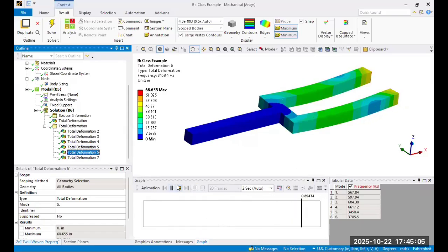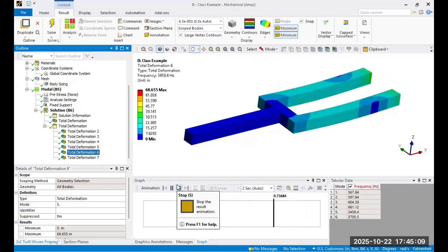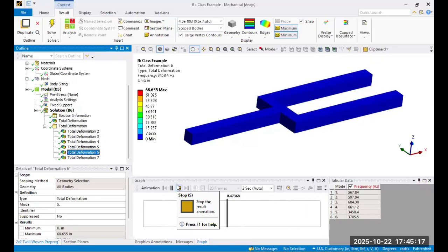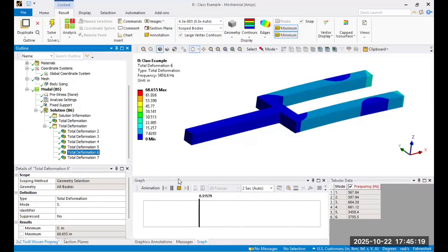I'll give you another example where I've seen the most failures. And this is tubing in a launch vehicle. Tubing also in aircraft and other applications. So a lot of times you have a significant amount of tubing across an aerospace structure. If the tubing is not sufficiently supported, say you have 12 inches with no support, or 13 inches, the longer you go unsupported, the more frequencies are going to come in, and the fundamental frequencies of that tubing will drop lower. Because if this was longer, the fundamental frequencies will become lower.